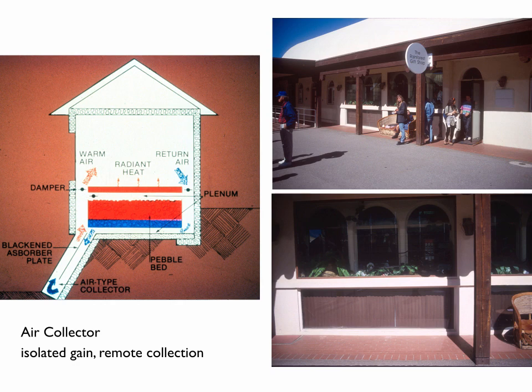And then there was another passive loop of air that was going into the space with dampers that could be controlled and so forth. That's a really hard system to make work effectively. Some of those buildings worked, some of them did not work at all because it's pretty hard to make air make right-hand turns when it doesn't want to and things like that. So later on, we began to add fans to the system, and that tended to be much more predictable.